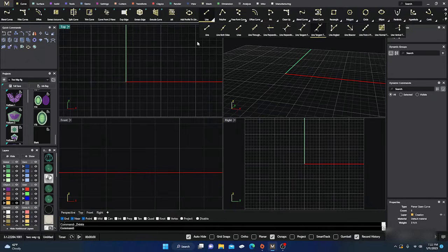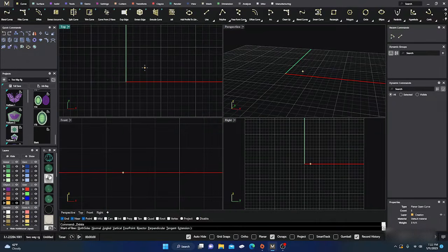And then if you just click on the line, for example, you come down to your command line and you can choose both sides. If I click the line on and go to both sides, when I click, I have a line that extends both sides. If I bring back that command by right clicking, you can go to the normal of whatever surface or line. Angled, you can type in a direction, a certain angle. Vertical, straight up and down.